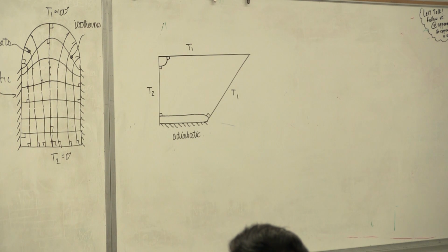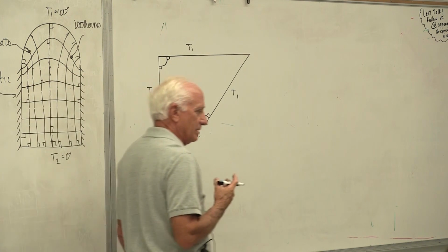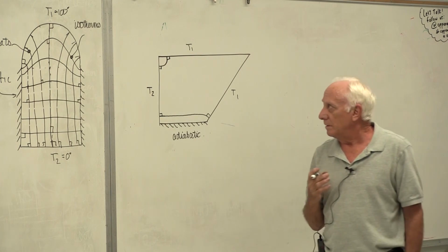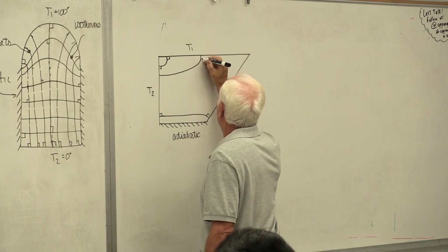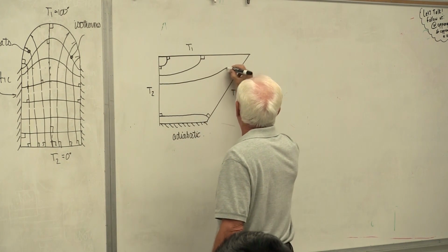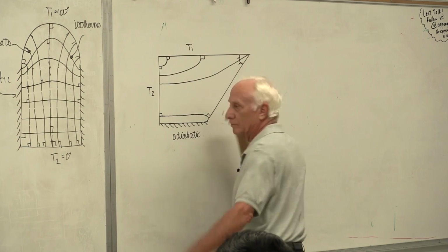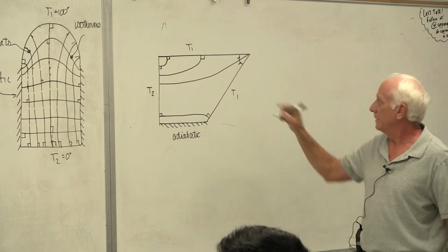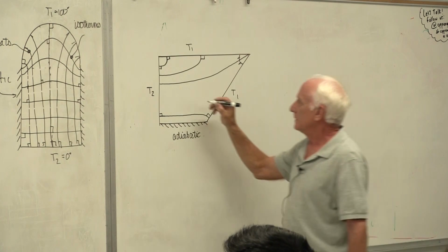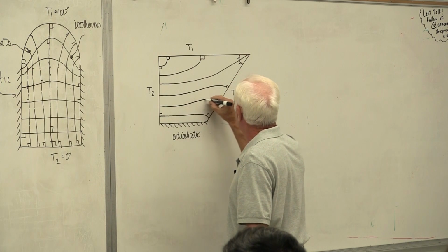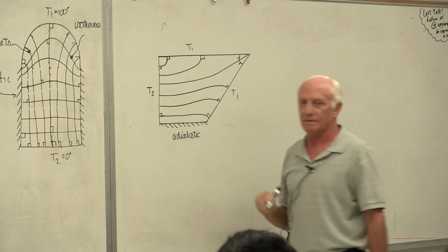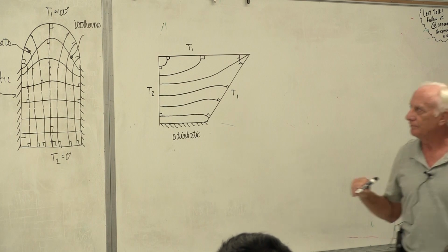Now I've got two heat flow lines drawn, adiabats. Try and draw the ones that make the most sense to you first. Then fill in the middle, the blank area. Okay, filling it. Comes out here, goes out there. Comes out here. Oh, I think it might bisect that corner. Rule 5. Yeah, isothermal corner. Comes out here, goes out there. Comes out here, goes out there. Yep, there they are. That's the heat flow lines.